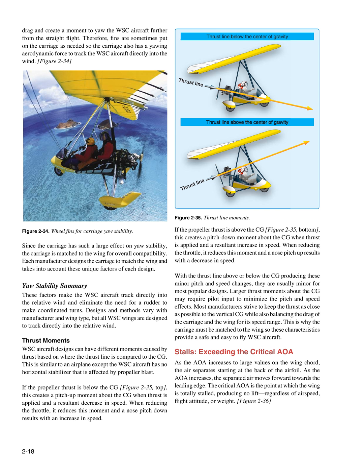As the AOA increases to large values on the wing chord, the air separates starting at the back of the airfoil. As the AOA increases, the separated air moves forward towards the leading edge. The critical AOA is the point at which the wing is totally stalled, producing no lift, regardless of airspeed, flight attitude, or weight. Figure 236.